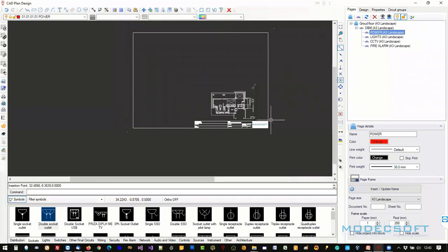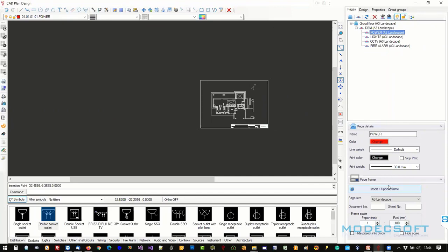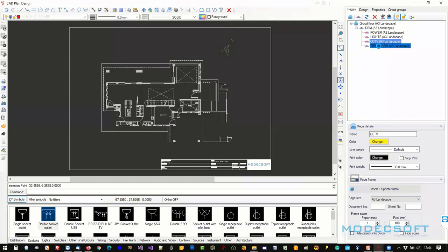So this is a clarification that is important to understand. Don't scale the drawing, don't scale the figures. If you want to print them on a larger page or a smaller page, don't scale them. Just scale the frame. This is the way you have to do it. And then of course when we have this setup, you see that even if I select something here, it's zooming always to the same location, meaning that the frames are placed on the exact location.